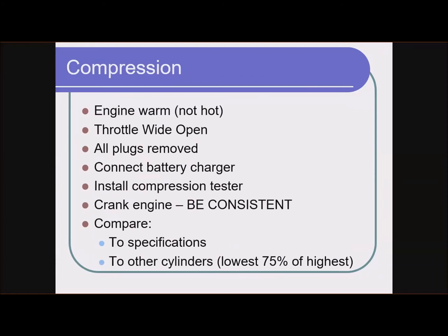The reason we don't want it hot is there's a little bit of a problem with removing spark plugs. Didn't used to be that big of a problem when cylinder heads were cast iron, but now that most cylinder heads are aluminum and spark plug shells are still steel, these two materials have different expansion rates.